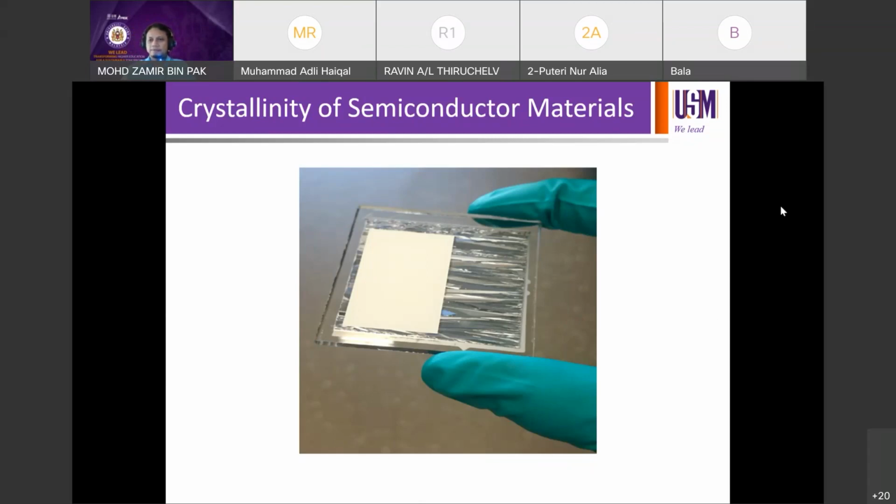How about poly or multi? Grains. Okay. All right. Other stuff for multicrystalline or polycrystalline? They have grains. Okay. Other keywords around polycrystalline? Different reflection level. Okay. You can tell by different colors. So if the grains are big enough, you can see them with the naked eye. If the grains are not big enough, you probably cannot tell the difference. You still have to go to a specific characterization in order to tell. Right? How about the third one? Mono.